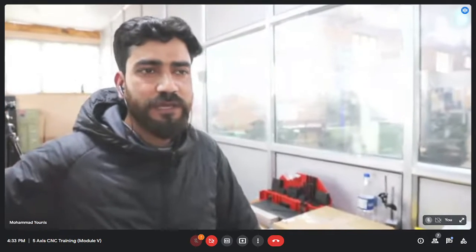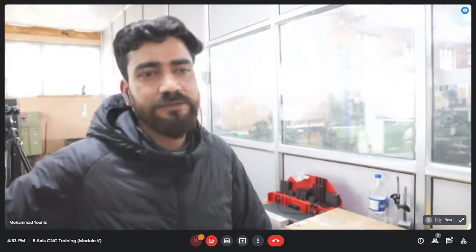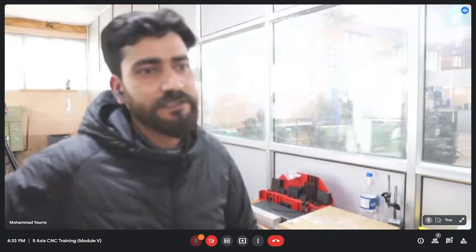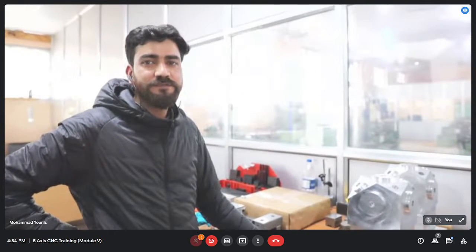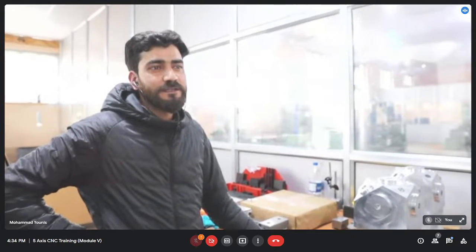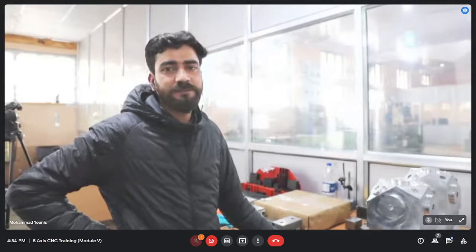And for now, we have just used a 3+2 axis, or I can call it a cycle 800. In these machining programs, we have provided simultaneous movement only to 3 axes, and then for 2 axes B and C. So this is actually not a simultaneous 5 axis machining. That simultaneous 5 axis machining is possible only with the help of some CAM software.